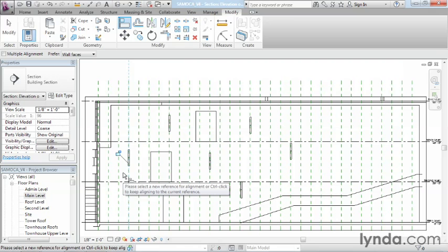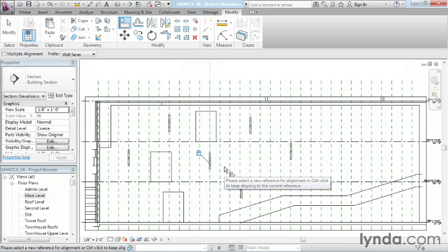The advantage of locking them is if you anticipate changing the spacing of the reference planes, like I showed you a few moments ago. So if you're not settled on the 5-foot spacing yet, and you want to try varying it around, then it would be a good idea to lock these. Align it, lock it, align it, lock it. When I did this, sometimes I used dimensions to set the vertical. Sometimes I just eyeballed where I wanted them vertically. You can get as detailed with this as you want to get.